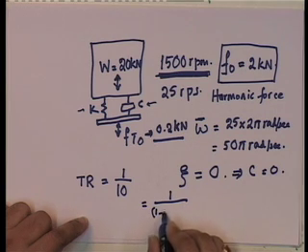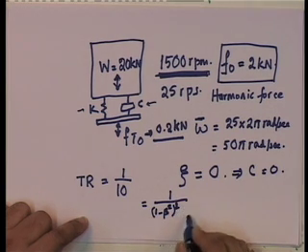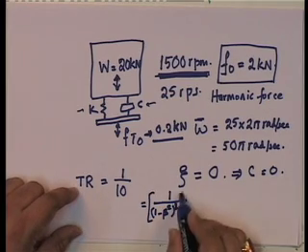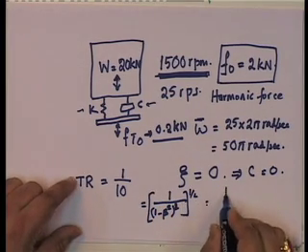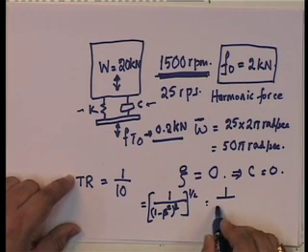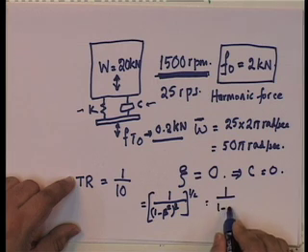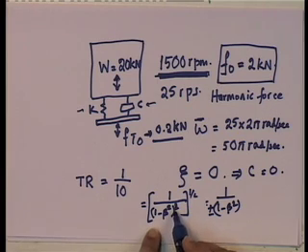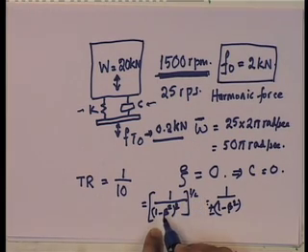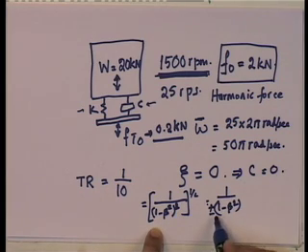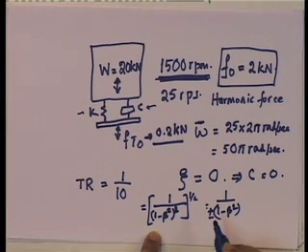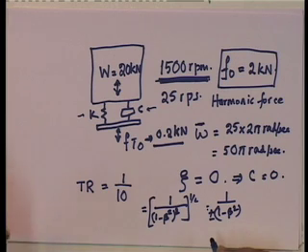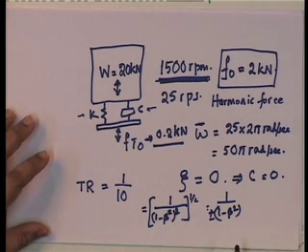Then we have 1 minus beta squared plus 2 xi beta, that disappears. This is square root. So, this becomes 1 upon 1 minus beta squared plus or minus. Remember that when you do this squared and then you do the square root, the square root is not necessarily 1 minus beta squared. It is plus minus 1 minus beta squared, whichever value is needed to get us a realistic picture.